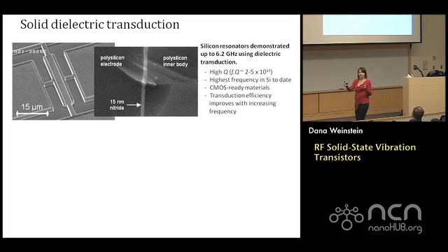On the other side, if I have vibrations in the structure and I have a voltage across this capacitor, well, the capacitance is changing as this beam is moving, and I can detect a current at the output, right? Well, if we fill in that air gap with a dielectric, we can still do the same thing, but now instead of measuring displacement, we're measuring strain, right?